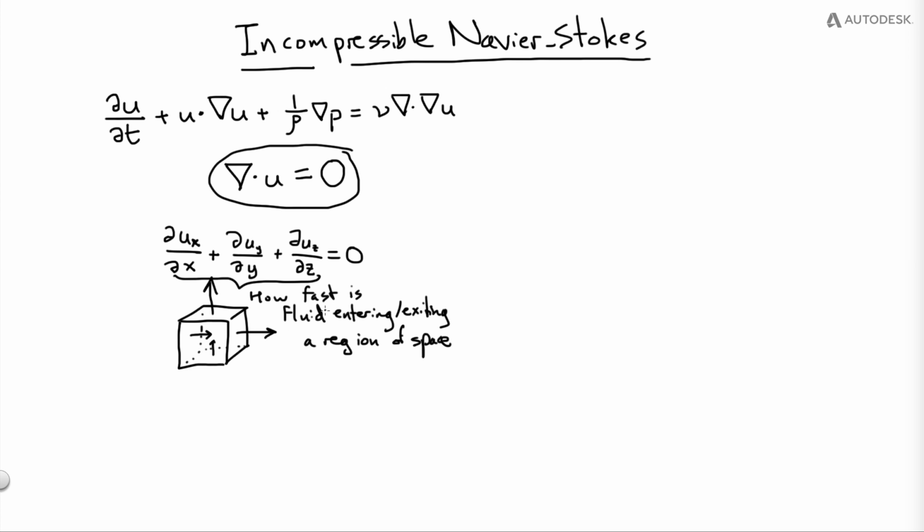And this is basically saying that the fluid conserves its volume. Although I'm sure I've heard that's always true for liquids, you might be saying, well, that's not quite true for gases because you can compress them in a pump or things like that. But of course, those are unusual situations, and most of the motion is governed, it turns out, very accurately by this constraint. So let's go back to the other equation here.